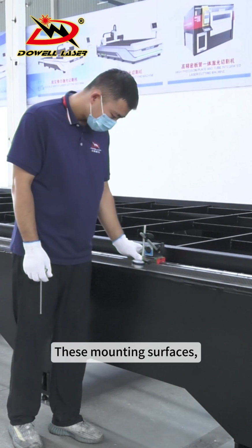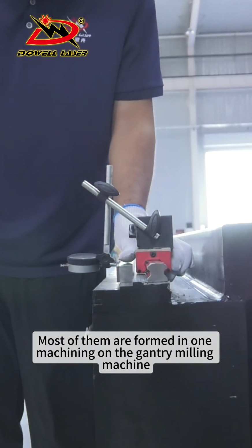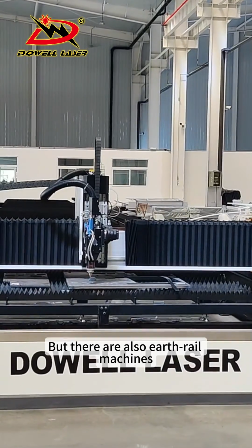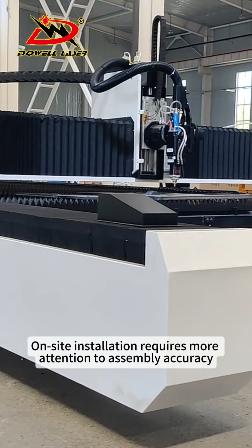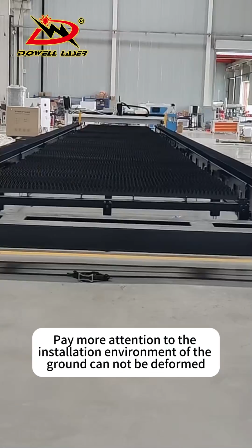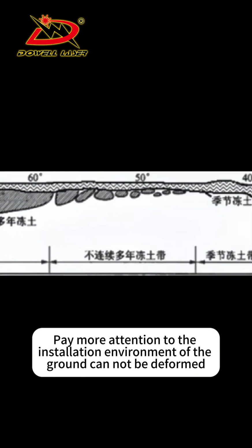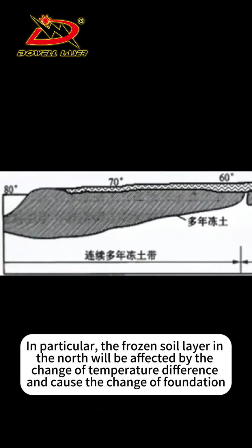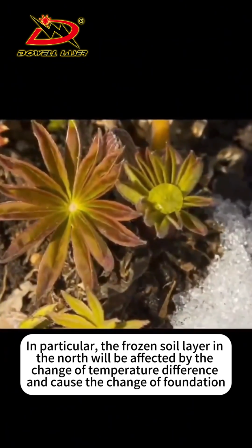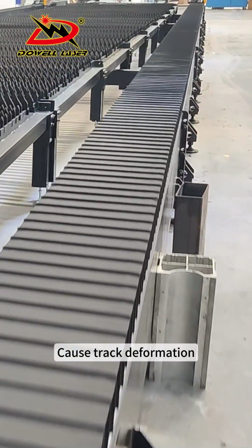These mounting surfaces, most of them are formed in one machining on the gantry milling machine. But there are also ground rail machines. On-site installation requires more attention to assembly accuracy. Pay more attention to the installation environment, as the ground cannot be deformed. In particular, the frozen soil layer in the north will be affected by the change of temperature difference and cause the change of foundation, causing track deformation.